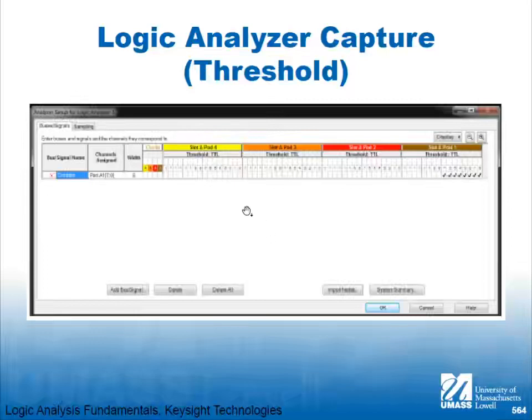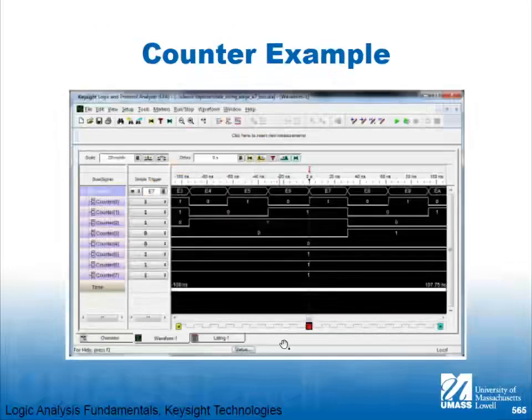So in a counter, right, you can see the least significant bit of the counter, 0, 1, 0, 1, 0, 1. The next 0, 0, 1, 1, 0, 0, 1, 1. Then 4 ones, 4 zeros, and then presumably 8 zeros and 8 ones. So this is what that count would look like if I probed it on a logic analyzer and I used synchronous